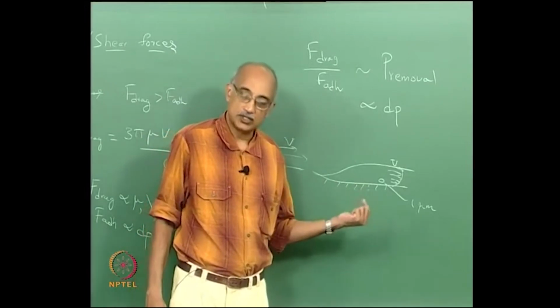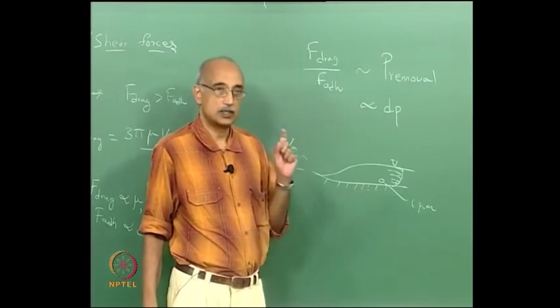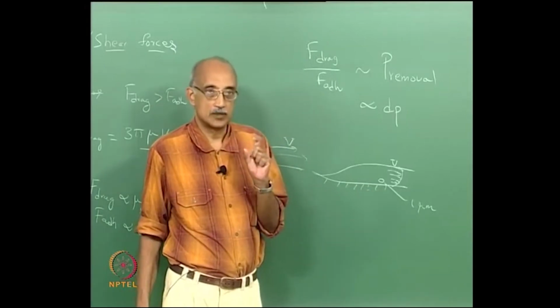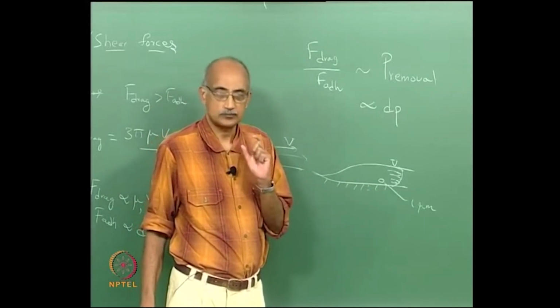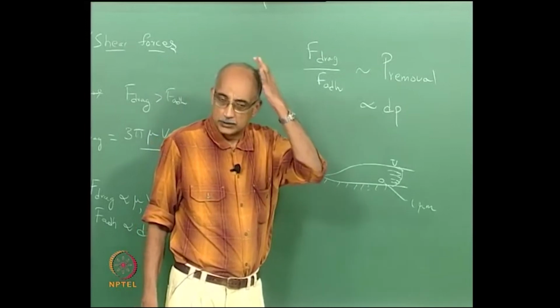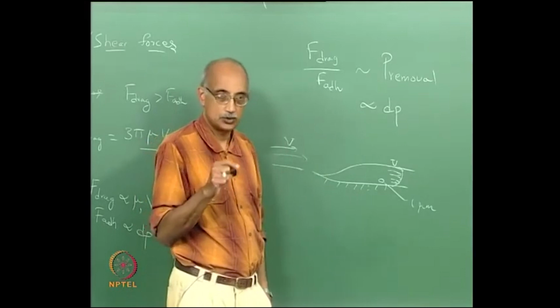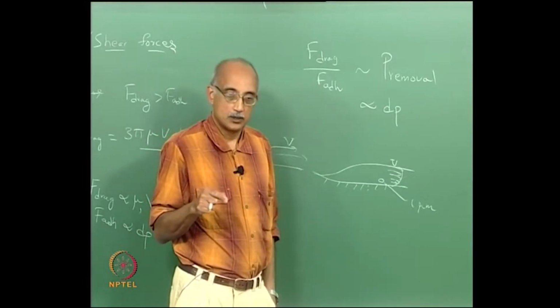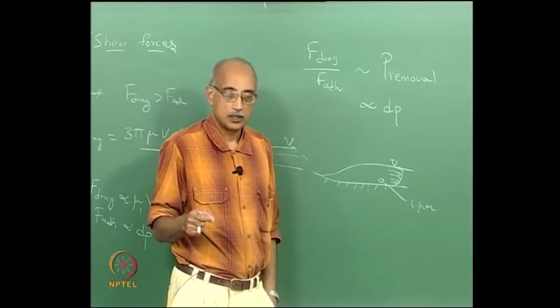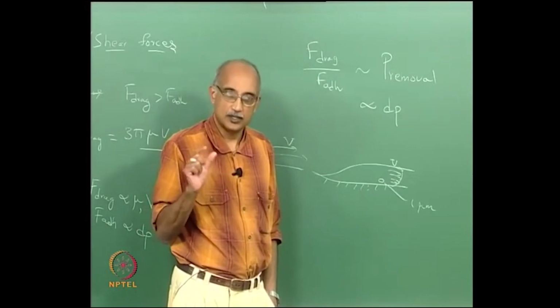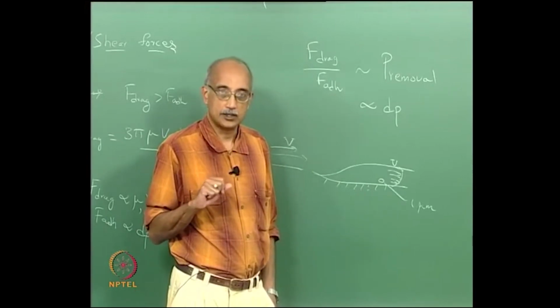So what is the strategy to address that? You have to try and make the boundary layer as thin as possible. How do you do that? Again, going from gaseous media to liquid media makes a difference. Which one has a thinner boundary layer, gas or a liquid?